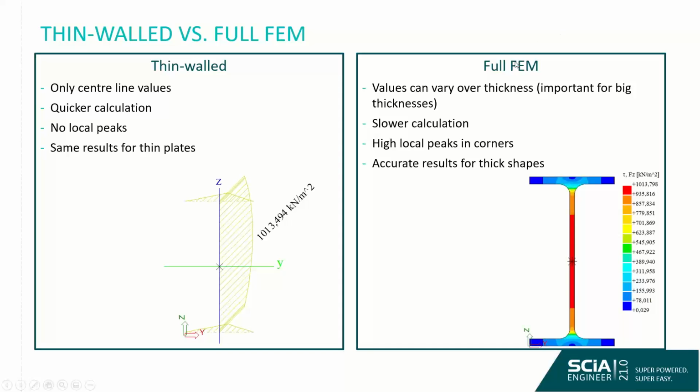Yeah. So when does full FEM become important? Well, if you are not able to have this centerline representation, or if your thickness is too high to be considered as a thin-walled section, and you need to take into account the fact that stresses can vary over the thickness of your plate.